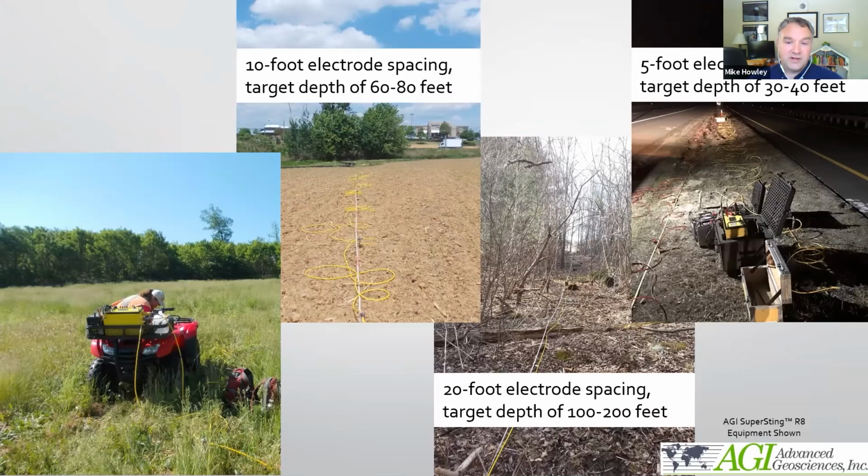A very important part of designing a resistivity survey is knowing prior to the survey the target depth, size, and resistivity contrast. The inter-electrode spacing is adjusted to maximize the likelihood of detection while maintaining productivity. Rule of thumb for depth of investigation is approximately 10 times your electrode spacing is your maximum effective depth of investigation. It does vary with array type and the resistivity of the soils in the subsurface.